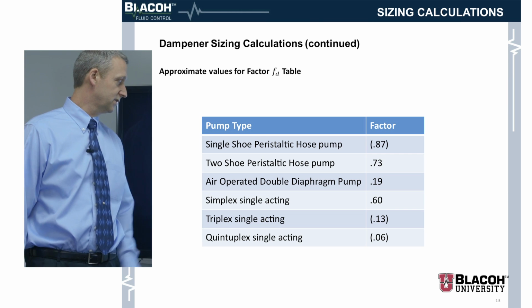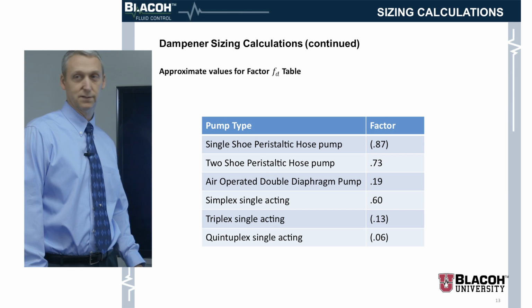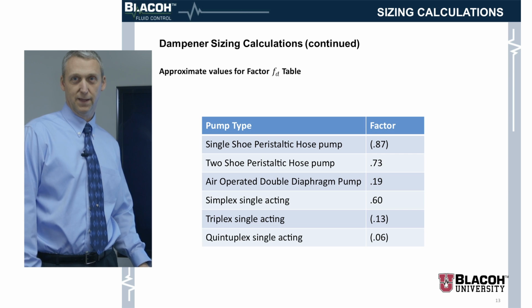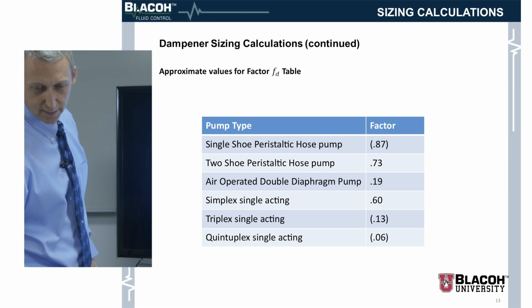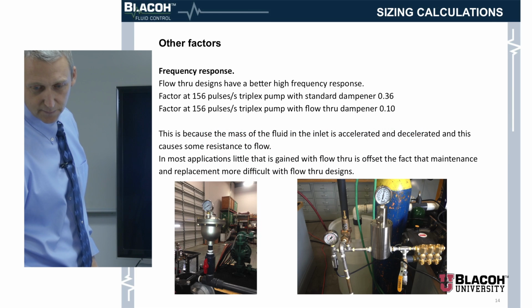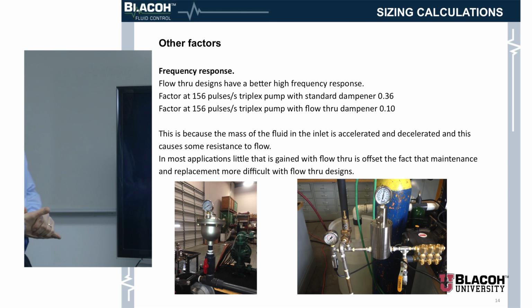It doesn't need a huge dampener, but in a lot of cases, these Quintuplex pumps have real high pressure, and you often want to put one on there to get rid of the pulses. All right, let's look at some other factors to consider.